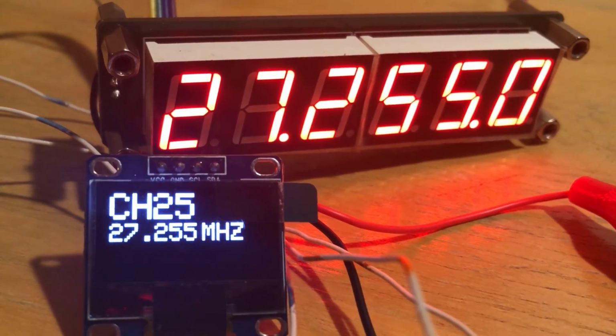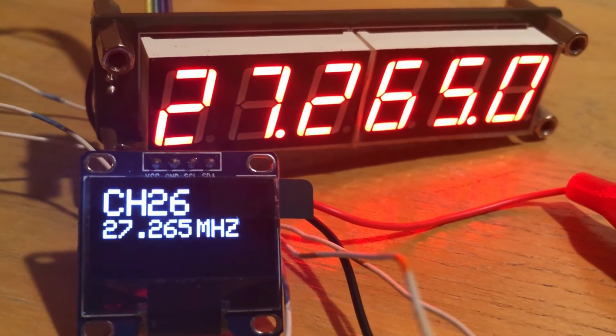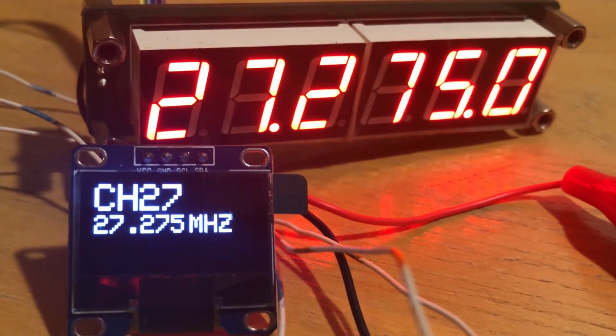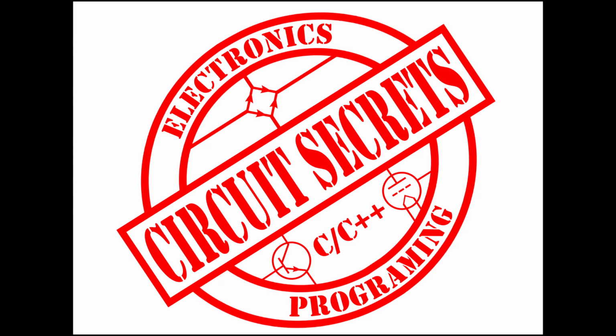In the loop, I can change the way display channel and frequency is called to generate a signal for calibrating a CB radio receiver. All it takes is commenting out the incrementing of the channel and setting the channel to the center of the band, say channel 20. So there it is, a working signal generator, and we are one step closer to a working CB radio VFO.